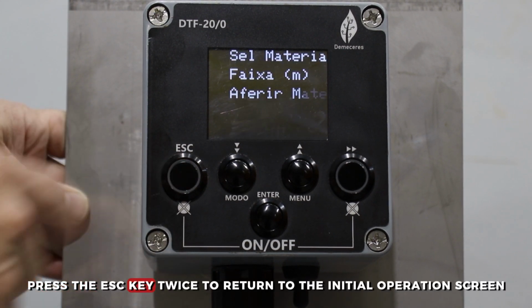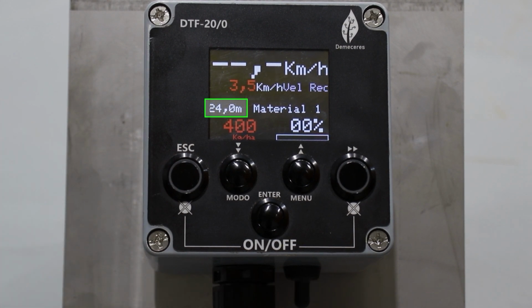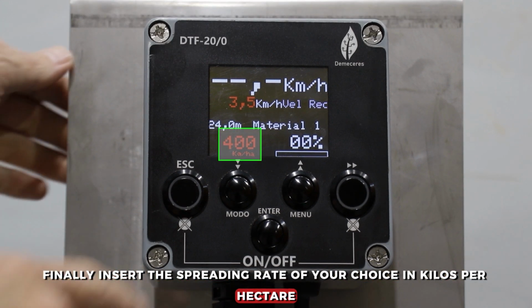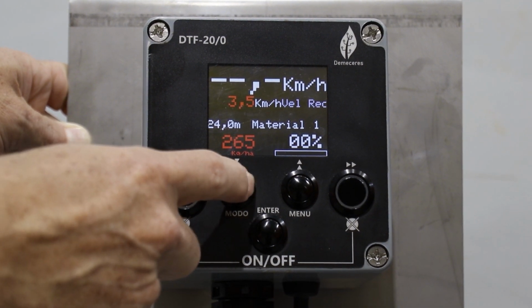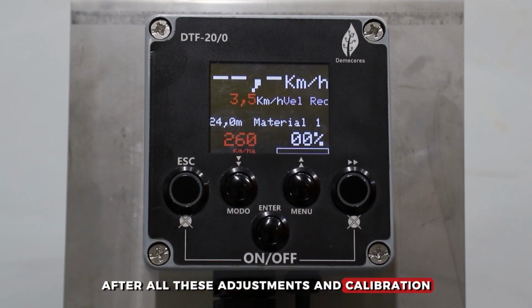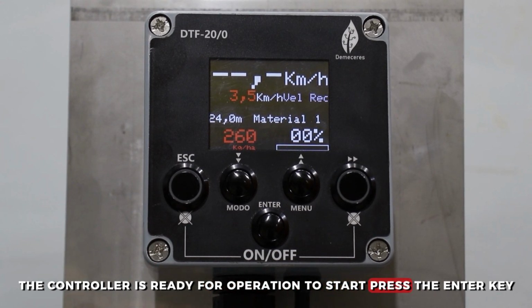Press the ESC key twice to return to the initial operation screen. Finally, insert the spreading rate of your choice in kilos per hectare using the up and down navigation keys. After all these adjustments and calibration, the controller is ready for operation. To start, press the Enter key.